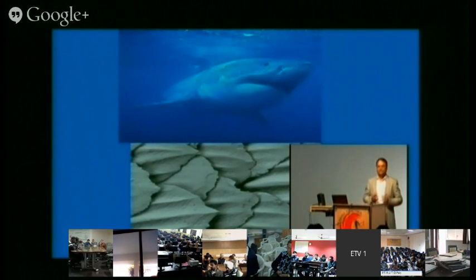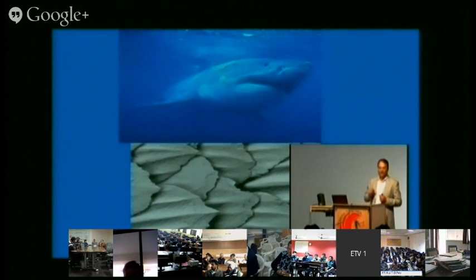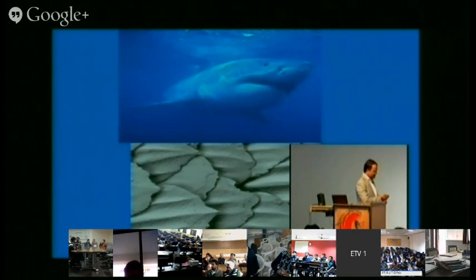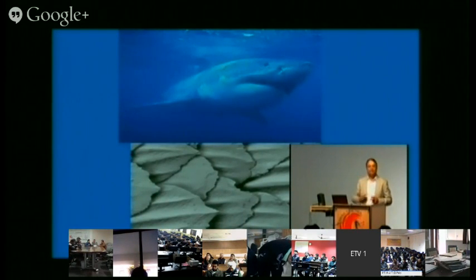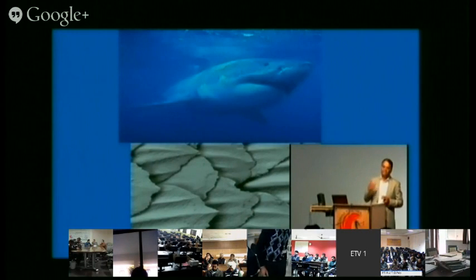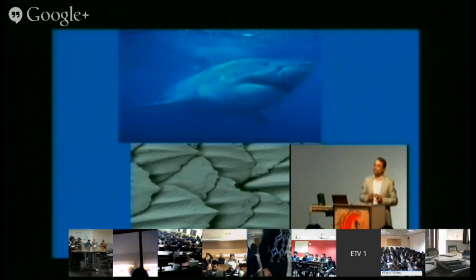It is quite clear that if this type of surface is there, with micro channels, micro canals, then mixing of the water won't take place. So at the skin, there won't be turbulent flow, only laminar flow. Another point is that very tiny dimples have been provided inside the micro channels. The meaning is that slip will take place and drag will be lesser. So nature has designed this surface to minimize the friction on the giant body of the shark fish.